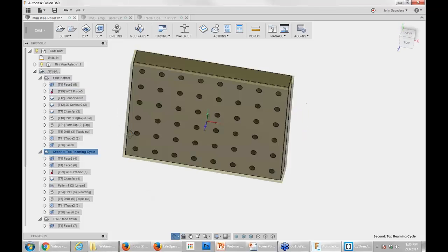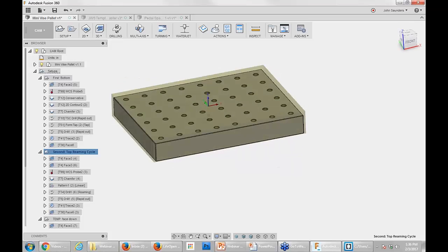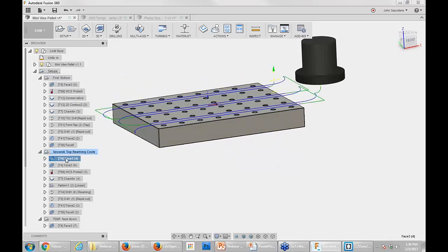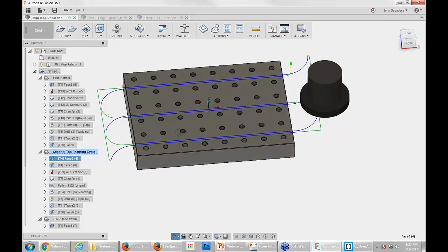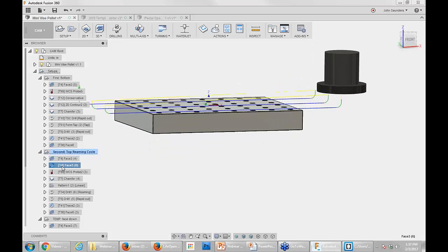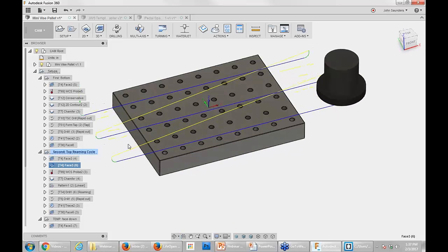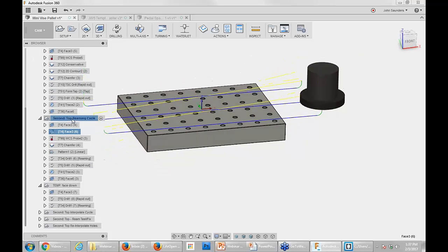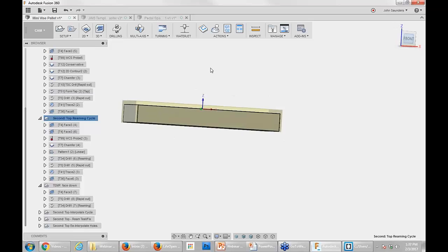And so the same part, just the flip side. I don't know why I have two faces here. Oh, great example. I'm doing a much heavier cut where I'm doing climbing and conventional machining to get off the excess, and then I'm doing a separate recipe, climbing only, to get my surface finish. There's a mushroom cap left over that you guys are probably all familiar with.